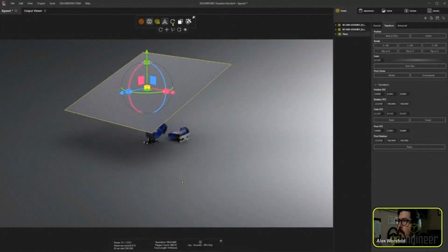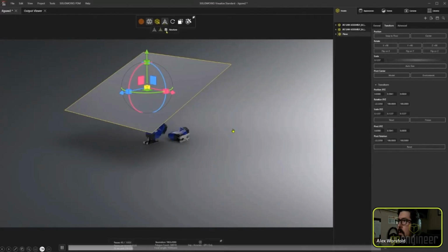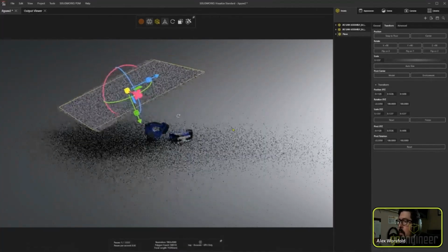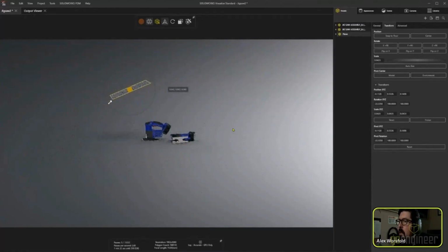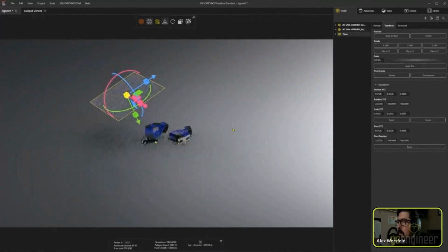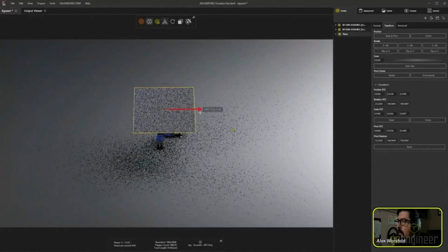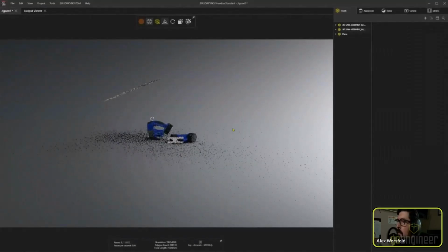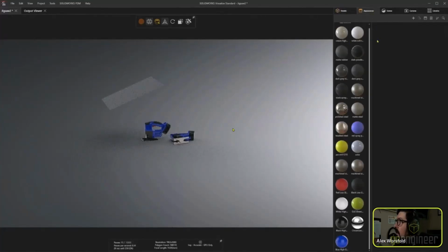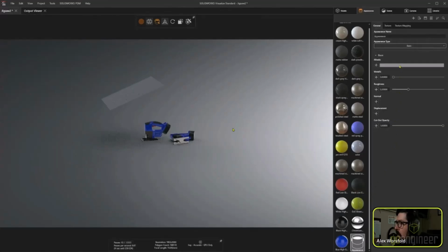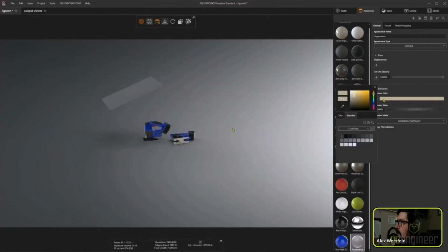I'm going to switch over to this absolute mode, so that I can see this arrow here. I want the green arrow pointing back towards the model, because apparently light is only emitted from one side of surfaces. That's how you can tell which side is emitting the light, with this little green arrow. So we need to create a new light appearance. I'm going to create a new appearance from a right click, and assign the type as emissive and change its color to white.